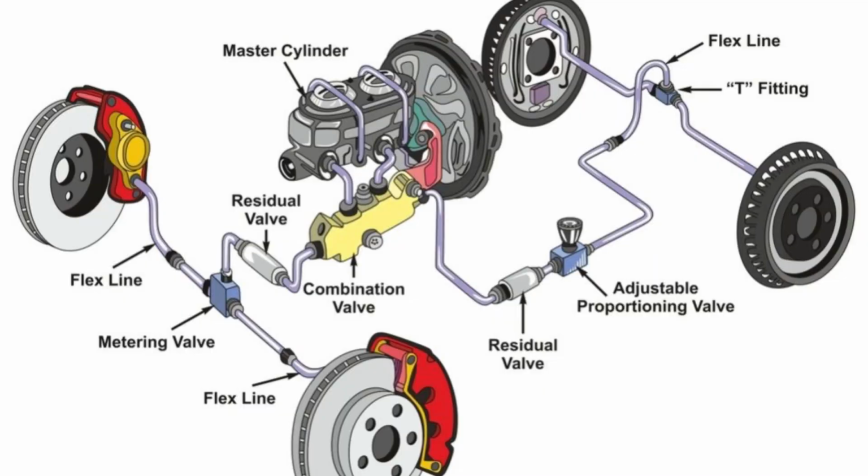Working of brakes. A common thing to understand about the brake system is that the brake does not just squeeze against the drum or the disc, after which the pressure of the squeezing action slows down the vehicle. Actually, the brakes take the help of friction: the brake shoes and the drums convert the kinetic energy developed by the vehicle into heat energy. Whenever the brakes are applied, the pads or shoes are pressed against the brake drums or rotor, which converts the kinetic energy into thermal energy through the effect of friction. Therefore, the braking system is essentially a mechanism which changes the energy.